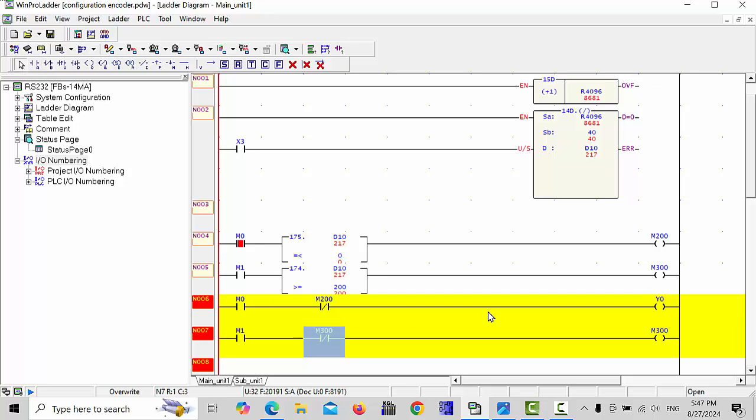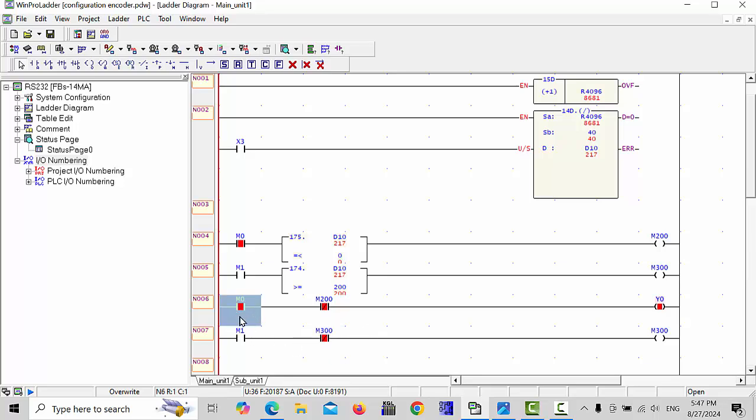and Ctrl+W, this select, and see when you make this one push button, this M0 is on. Now your crane is running back up, and your value will be going down, and as it reaches 0, after that your Y0 will be off.